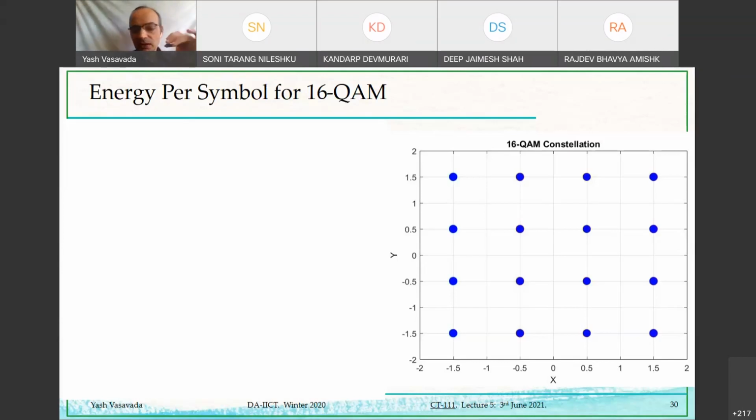Yeah, so we have said earlier that the probability at the receiver to confuse a particular transmitted symbol, let us say where my cursor is right now, to something else, maybe this one or maybe this one, the only thing it depends on is the distance between them. It is specifically given as Q function of d divided by square root of 2 N naught.